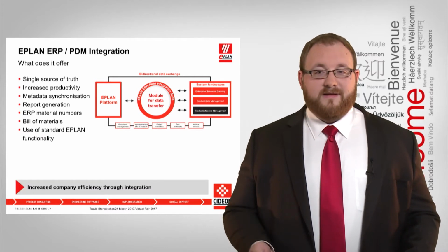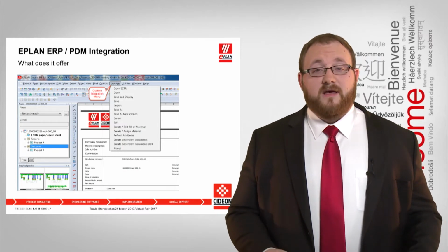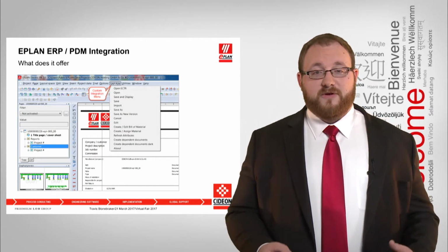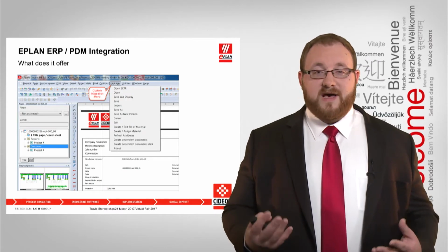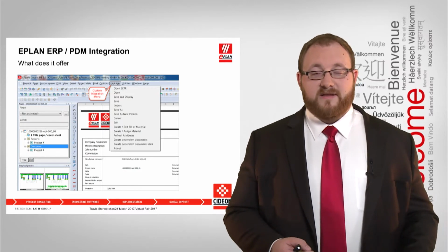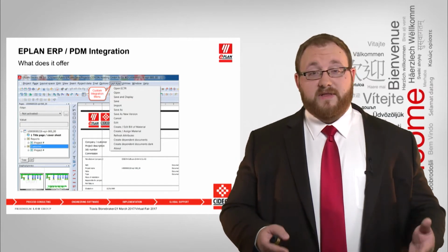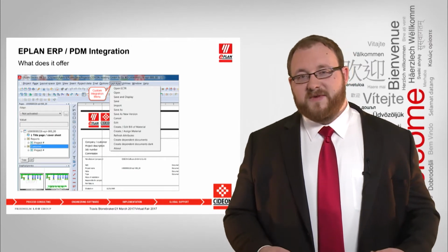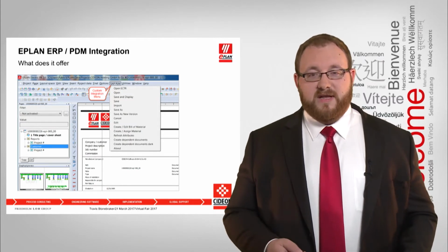For my next slide, this is actually what the integration looks like. Within Eplan, there is just a particular menu option that gets added to your environment. For me, I have SAP integration with Eplan. At the very top, you'll see SAP PLM, but this doesn't mean that there aren't other PDM systems out there that this can work with. You'll be able to see the options down below. For instance, you see create materials, build a bill of materials, and create dependent documents, which means these PDFs are the report generation piece that you can do automatically within Eplan.